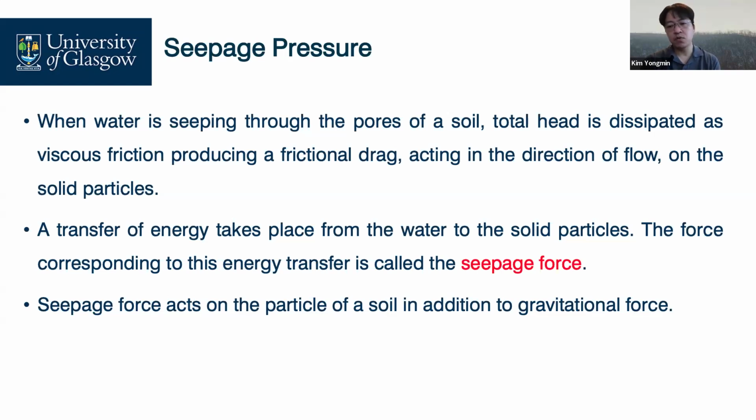Sometimes this seepage force causes instability of geotechnical structures when the seepage force exceeds the soil's effective stress. Mostly downward seepage increases effective stress, but upward seepage makes our soils have lower effective stress. We will deal with this phenomenon soon in terms of seepage force and effective stress.